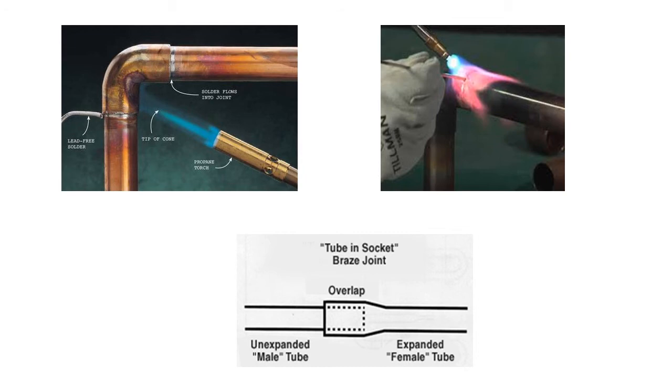The primary element used in solder filler metals is tin, because tin has an affinity for copper and wants to adhere to copper tube and fittings. However, the use of pure tin would make a very weak joint, and, as with any pure metal, would be very difficult to work with. Therefore, other elements are added to alloy with the tin to provide greater strength and make the filler metal easier to use. 95.5 solder wire is a lead-free alloy of 95% tin and 5% antimony. It has a melting point between 450 and 464 degrees, and it is a very common solder used in our field.